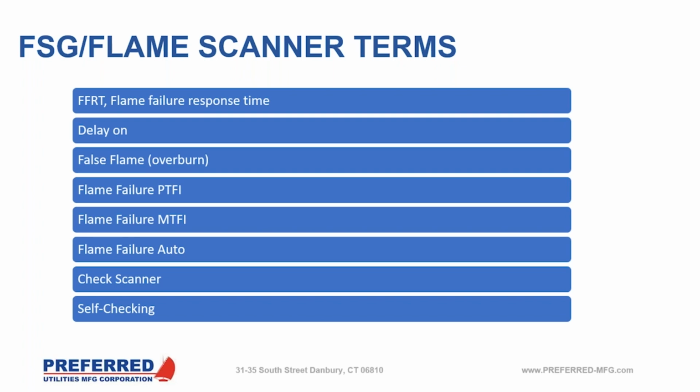Most of the time, again, it could be even a flame scanner sighting issue, and that's something that would have to be investigated. So again, this is another troubleshooting message that could come up in a lockout with a flame safeguard, but it's going to be during that second period of lighting the burner when we're bringing on the main fuel valves.